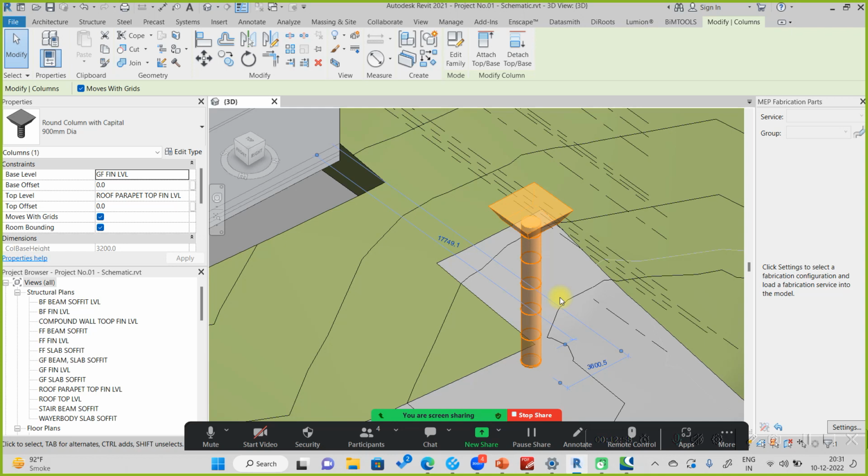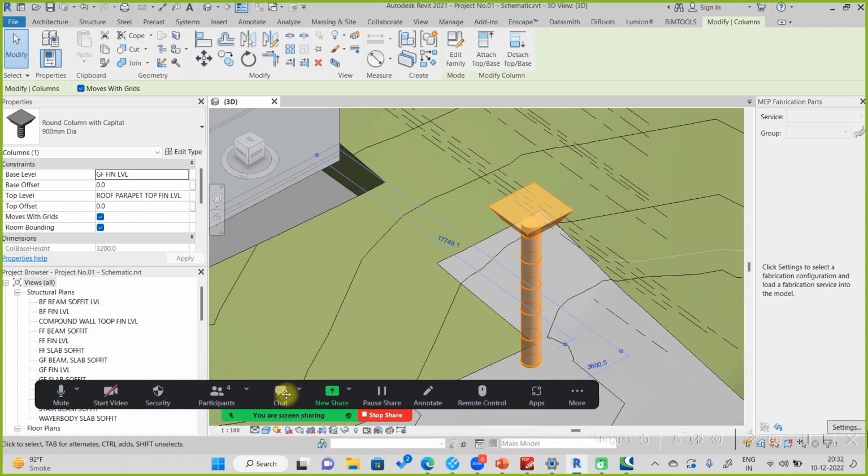Like if you are making an assembly, a kind of prefabricated wall, for example, and you want to make the panel of the wall a separate component and the stud framing of the wall is a separate component. So you might need to use this nested family in that setup, wherein the assembly kind of thing is coming, right?